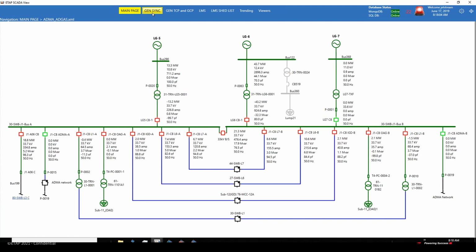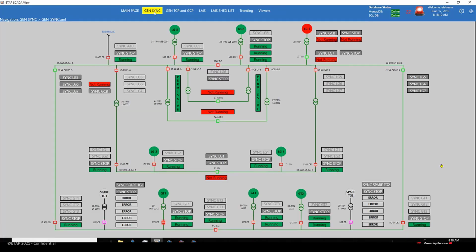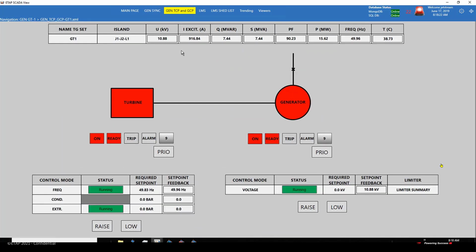You're not just limited to the single line diagram representation within ETAP. You can also utilize the SCADA visualization itself in order to have a better understanding of your environment. A SCADA HMI, including the generators and the rest of the system, could be more simplified and may represent either the ETAP SCADA or any other SCADA system, in which case you can select the generator that you would like to manage in an operator training simulation environment, look at the real power dispatch on the machine, and then raise or lower the set point of the generator.